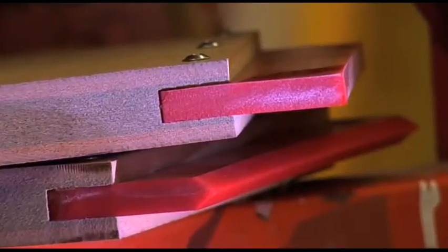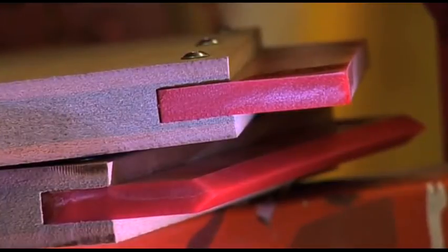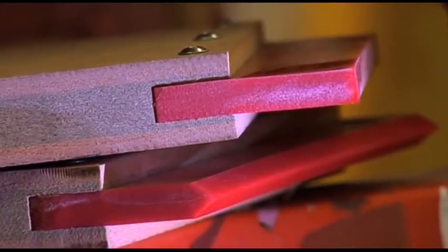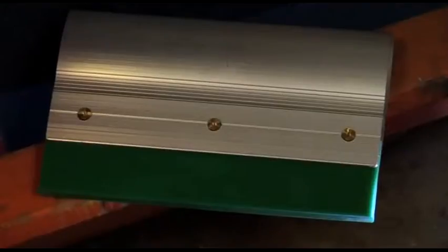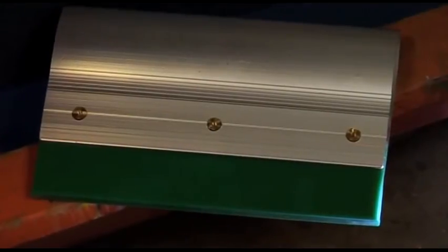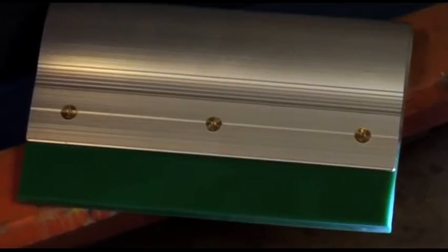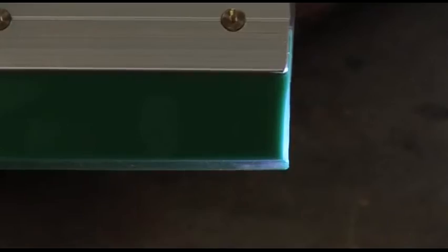There are 2 main blades of squeegee to choose from, one being a D-cut, also known as a V-cut, and the other a square cut blade. A D-cut blade is usually reasonably soft as the blade puts down a good deposit of ink. A lot of printers use the D-cut blade, ideal for printing light onto dark, block or bold printing. The square cut blade is often used for achieving good definition and sharp lines. We can supply various different square cut blades, which range from soft, medium, hard, and extra hard.